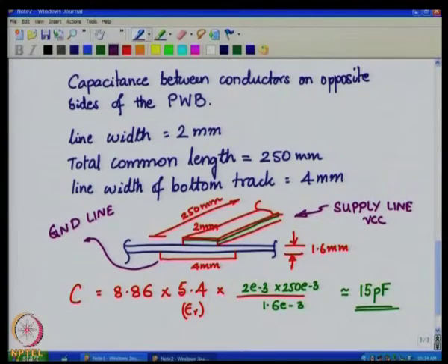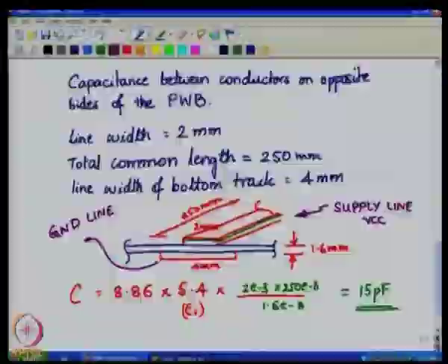These can be used as decoupling capacitors, a distributed decoupling capacitor, as these two lines are connected to various digital circuit loads, like we saw in the last class, the output stages of the gates being totem pole, composed of top and bottom switches, where during switching transitions you will have huge current spikes. So, it is always good to have a higher value of capacitance between ground and supply, lowering the impedance such that the supply and the ground lines are more stable.